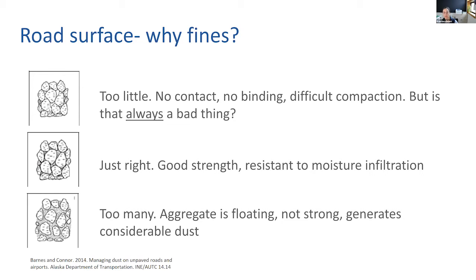And for that reason as well, we do have the larger rock at the bottom of the road and a smaller rock on the top, because we don't really need that much binding on the bottom. We actually just want the water to flow down from the surface.